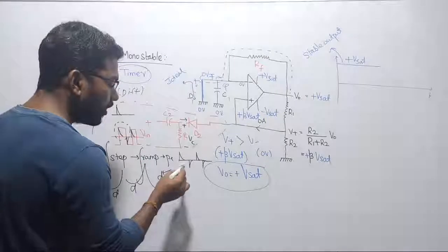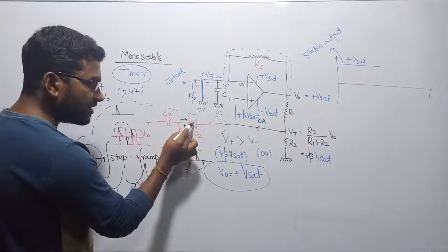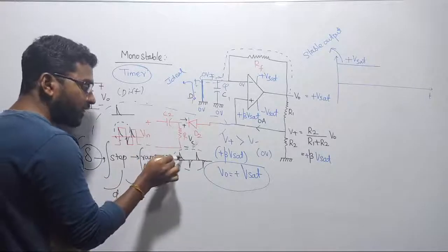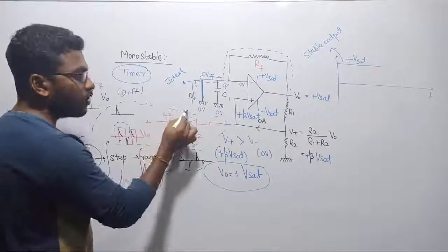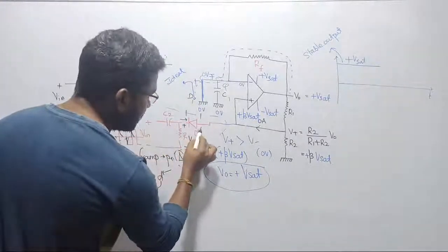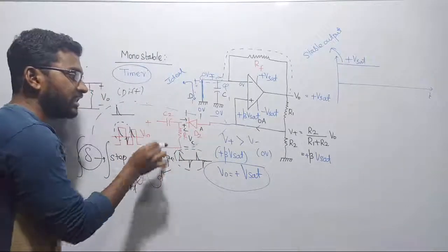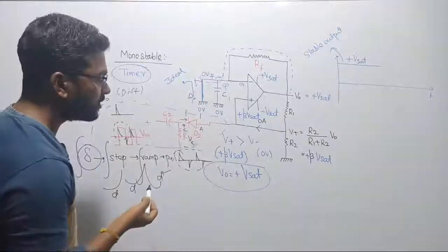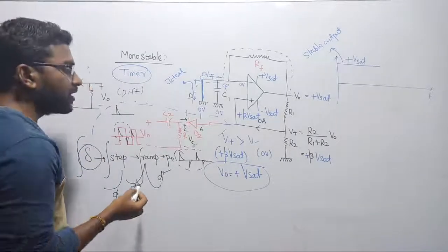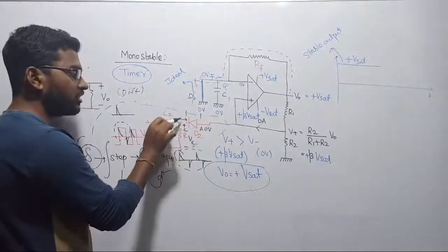Coming back. Okay, sir, when we pass this spike output to the diode, what will happen? See there, this diode is connected in reverse bias. Correct? On the positive spike across the cathode, the diode is open circuit. Why? Because this diode will turn on only when the voltage across the anode becomes greater than the voltage across the cathode. When we are injecting more positive voltage across the cathode, the diode won't respond. Let us assume initially there is no anode voltage, so here I have 0 voltage, and here I am going to inject positive voltage first.